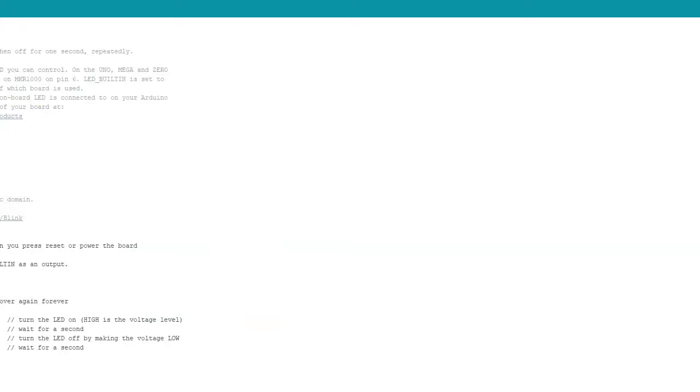So the first thing you do is compile the sketch or verify it. When you're done, you see down here there's a message that says done compiling. So that's good. That means there are no errors. Now we need to upload it into the Arduino's memory. So we're going to click Upload.